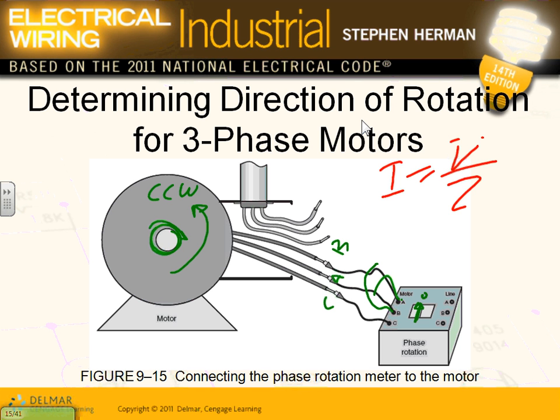The voltage that I showed you, the first one, that's just lowering it within 10% of the nominal value. So 480 plus or minus 10%, that will get you higher or lower amps. If you lower it substantially, as in cutting it by half, 1/3, like we do with the start, it actually cuts the current down. That's how I explain it to myself.